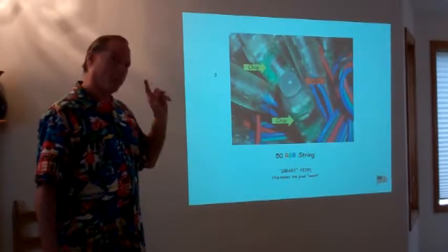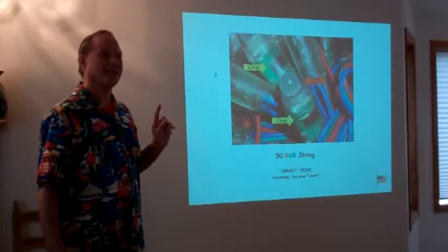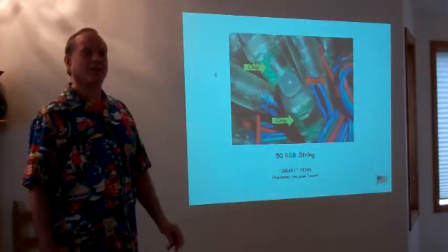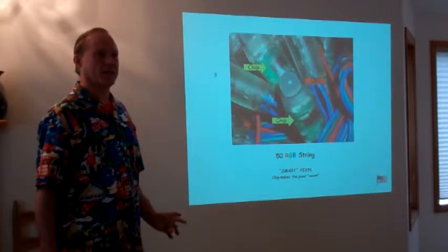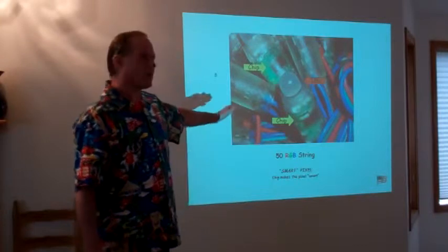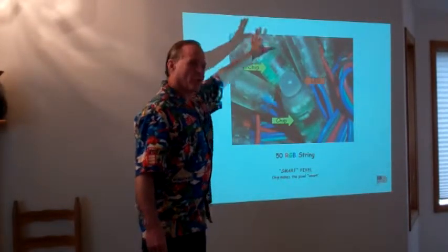What do I mean by smart? That means that one pixel by itself can change up to 6 million colors by itself. That means all the rest of the devices, all the rest of the pixels in that particular string can do the same. If that chip is missing, that means that whole string then would be one color. So if this was blue, all the rest of them would be blue. But this way right here, we have the ability, yep.